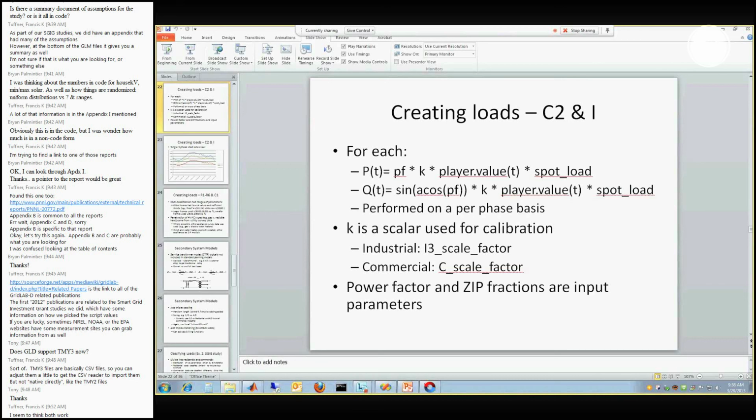Right. Yeah, something we ran into a few years ago where we were scratching our head. It's like, why can't we get any regulator action? What's going on here? And oh, the light bulb went off, it's on the source side. Yeah, exactly. The one caveat to that is if it's any kind of line drop compensation methodology. If they use an LDC, then you can see some action without varying the source voltage.